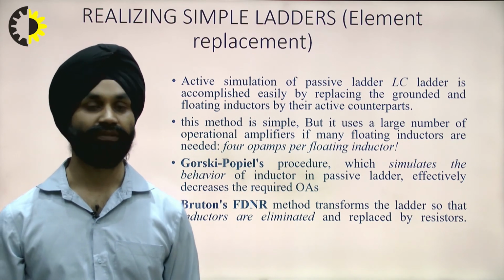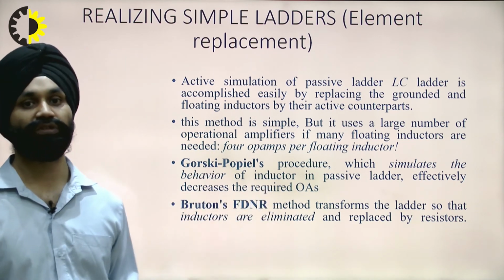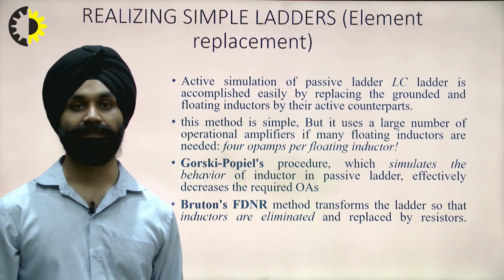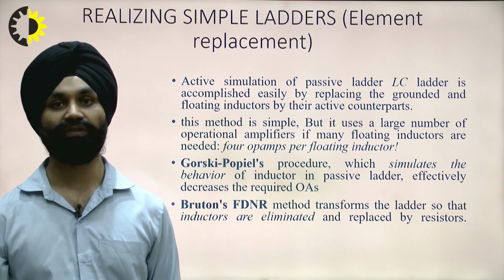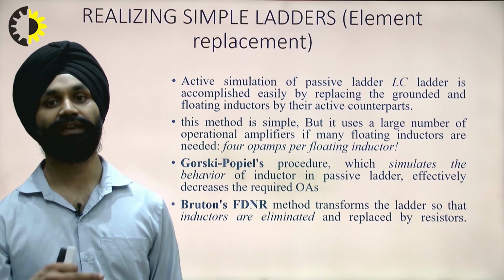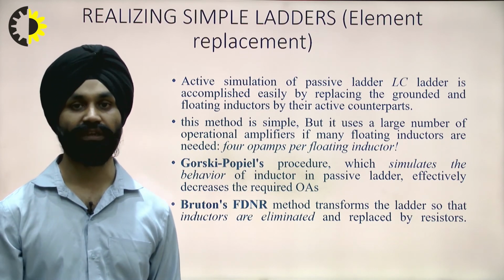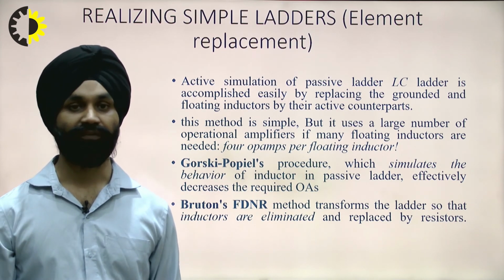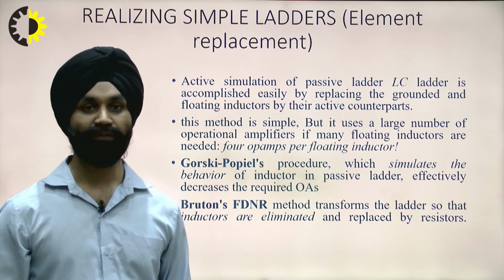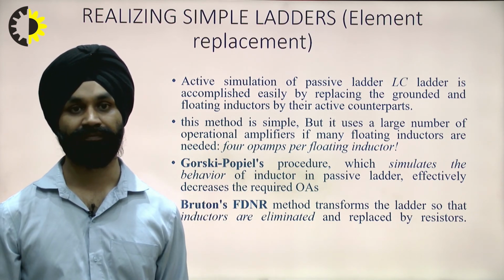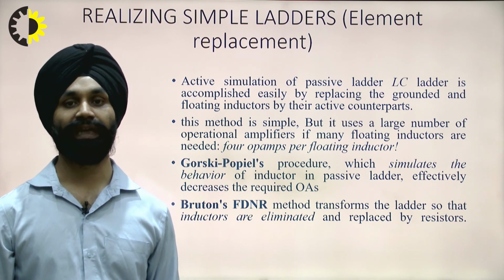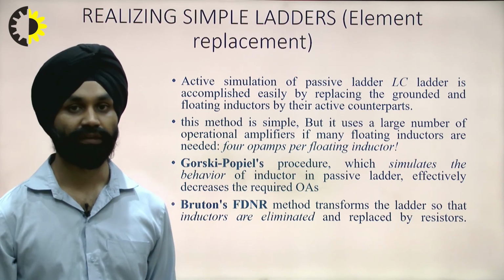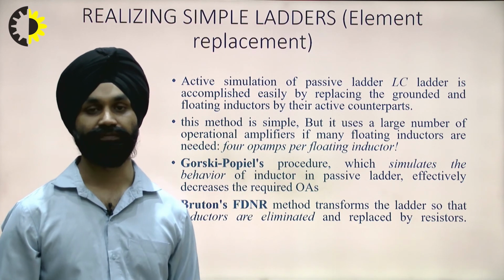There are other techniques known as the Gorski-Popiel technique and Bruton's technique. These two techniques also give a replacement of the inductor. That means we can realize this passive component using the active components. The first technique simulates the behavior of the inductor, so its behavior will be similar to the circuit proposed by the Gorski-Popiel procedure.